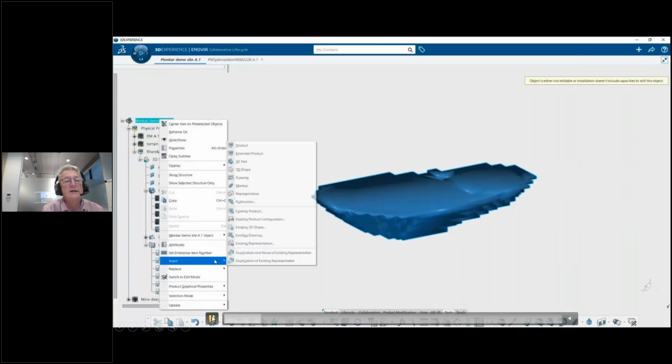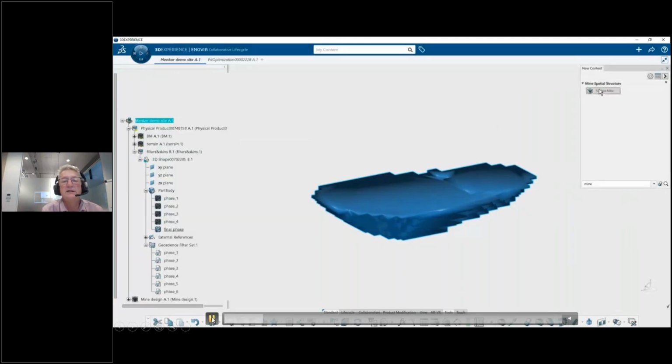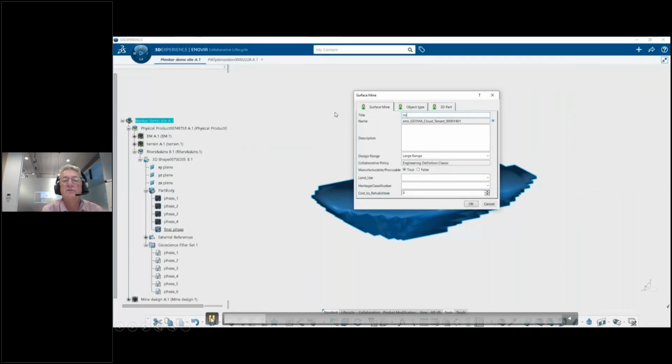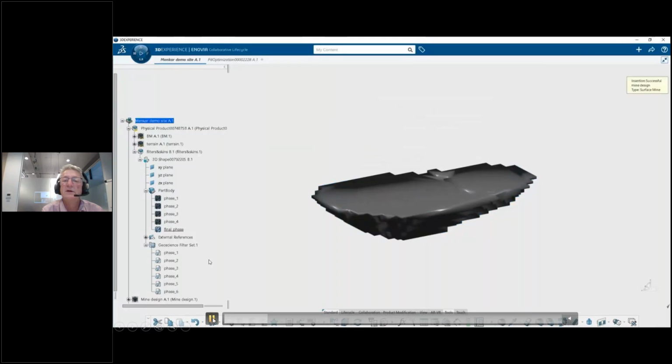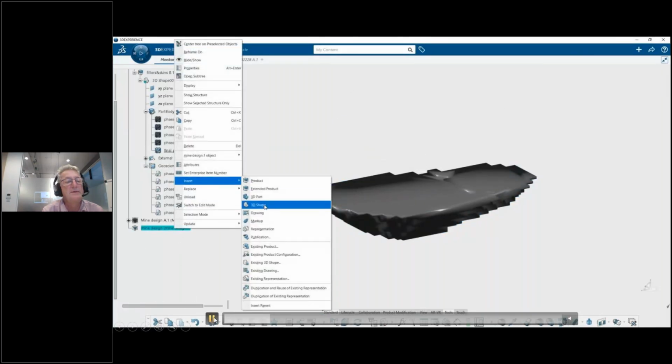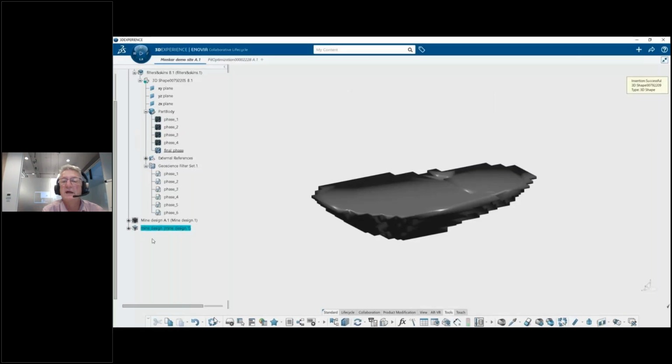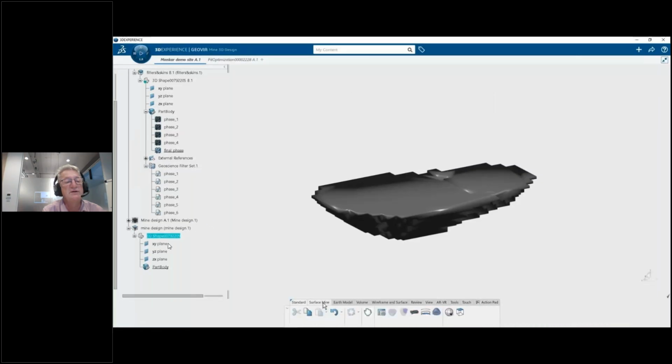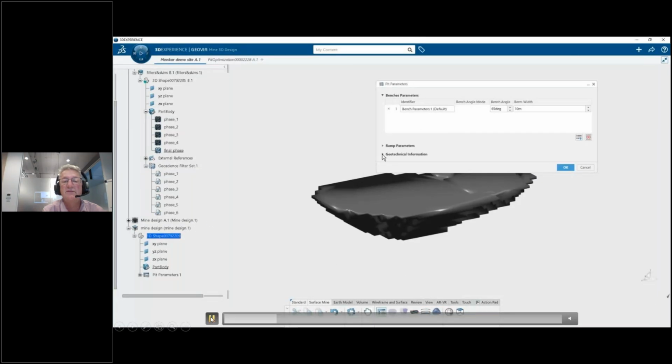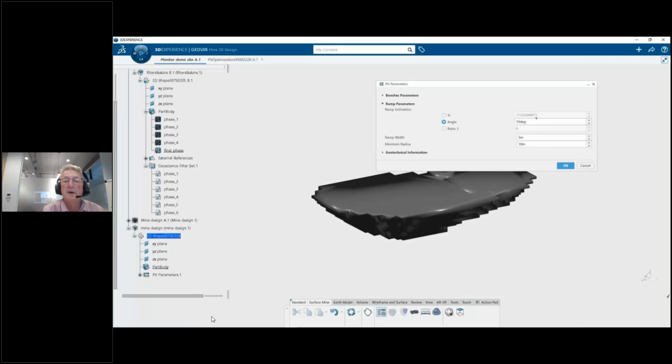The design is created using a series of parameters. The first set of those parameters defines the bench elevations and the bench heights, which are then used to apply the geotechnical parameters of berm width and face angle.